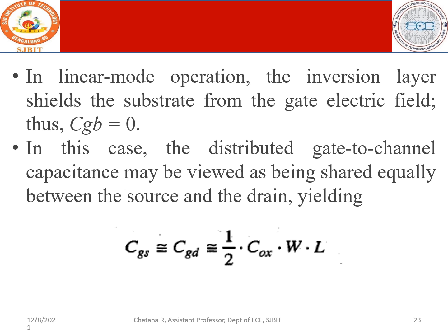The inversion layer acts as a shield for the substrate. Since the channel is now created and it is conducting, the substrate is free from any of the electric field impacts. Therefore, the capacitance at the substrate, CGB (body), is equal to 0.